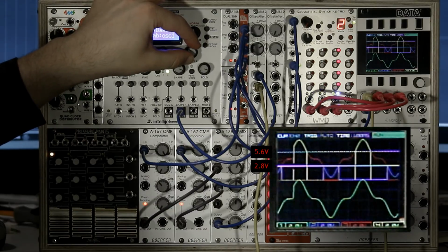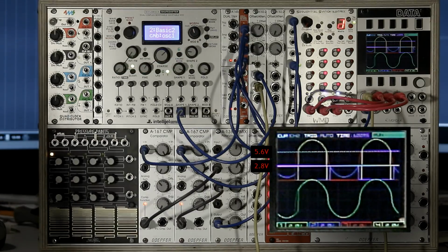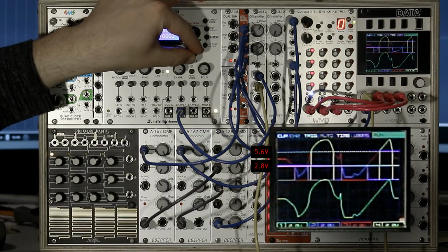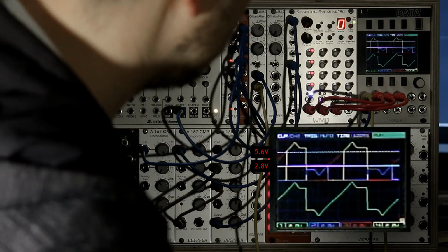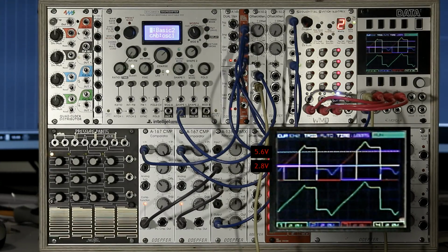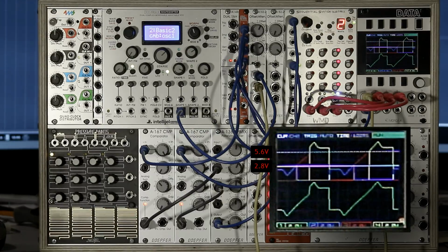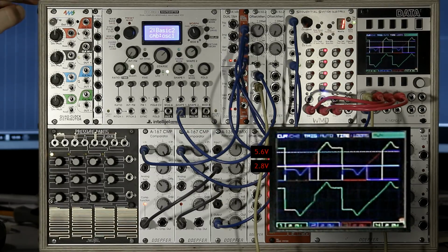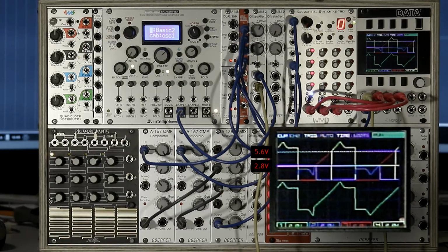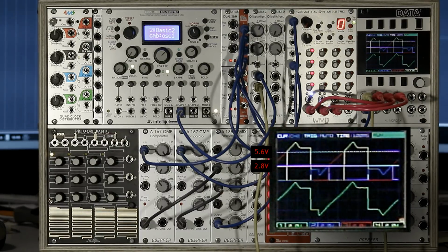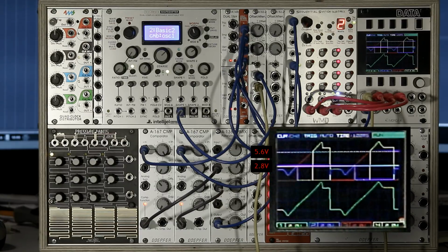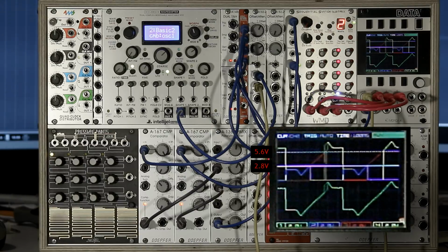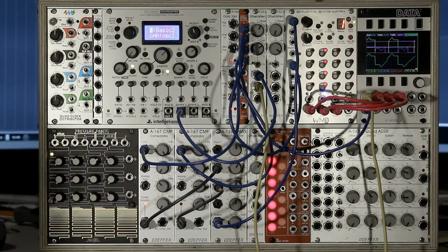This is a nice visualization, but if we want to create pitch CV for oscillators, this is not so useful. The signal appears to be split on screen, but it is a continuous signal and goes to 0 when the output is not passing the input voltage. Rather than switching the LFO signal, we can switch gates that will trigger different quantizer channels and use the continuous LFO signal as quantizer input CV. Let's create a clock CV and pass that to the sequential switch.